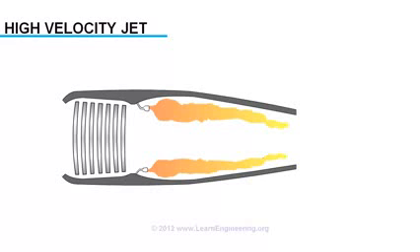Air gets into the engine by the forward motion of the engine and the sucking effect of the compressor. The diffuser increases the pressure of this fluid to some extent by converting some part of the kinetic energy to pressure energy. After that the compressor comes, where both pressure and temperature of the air are raised by energy addition from the compressor. So at the outlet of the compressor, we will have air at high pressure and high temperature. But the compressor requires some power input to do that.